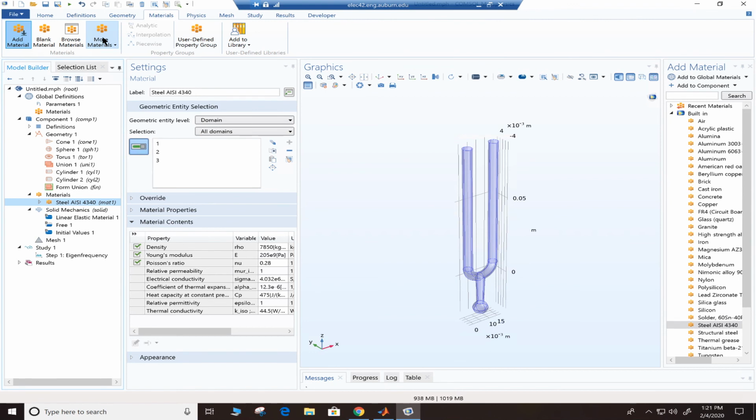And also, remember, in here, we remove those interior boundaries. This boundary right here, we want to keep it. And I'll show you in a second how we're going to mesh this little tiny boundary inside of here all alone. Then we're going to extrude that mesh up through the cylinder. So we need that boundary, so we don't want to get rid of that. But then again, you may ask, what if you unionize it but keep the interior boundaries? If you did that, I still think it will work.